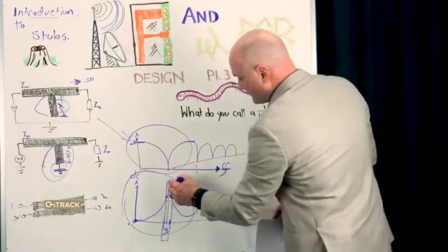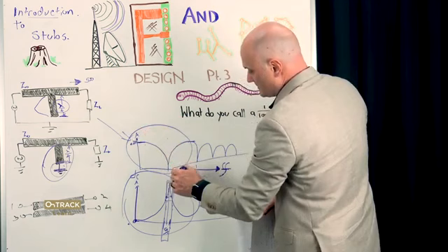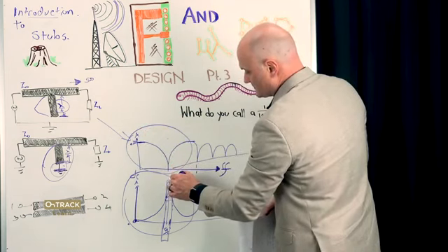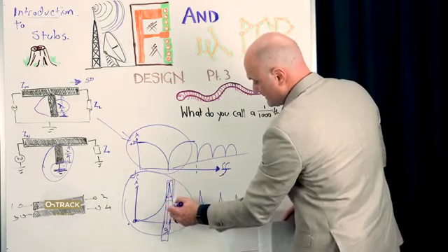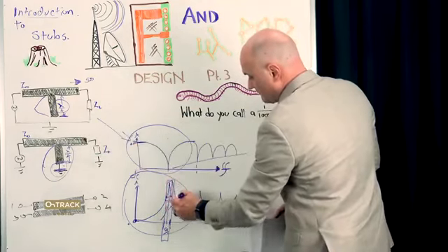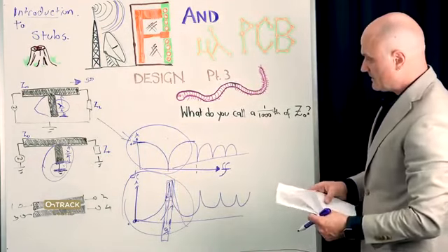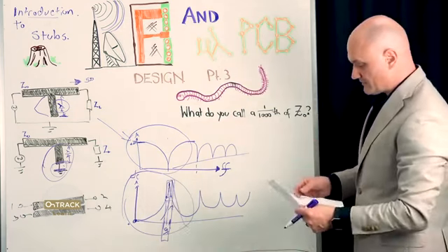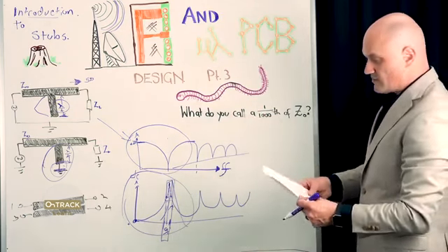But it's very important to build and test these so that you're as close as possible to your frequency of interest, because the slightest thing can shift the characteristics of this circuit and move it to some other frequency that you don't want it operating at. And this happens with antennas as well. So we'll talk about that more down the road, but let's walk through an example of how you might calculate this kind of thing.